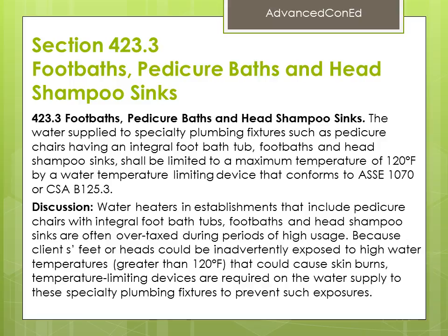Discussion. Water heaters in establishments that include pedicure chairs with integral foot bath tubs, foot baths, and head shampoo sinks are often overtaxed during periods of high usage. Because clients' feet or heads could be inadvertently exposed to high water temperatures greater than 120 degrees Fahrenheit that could cause skin burns, temperature limiting devices are required on the water supply to these specialty plumbing fixtures to prevent such exposures.